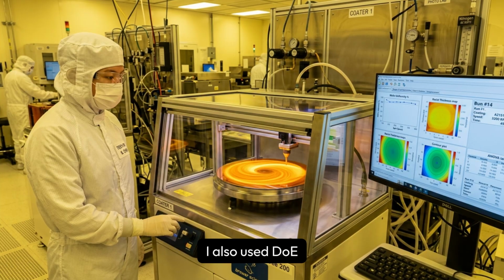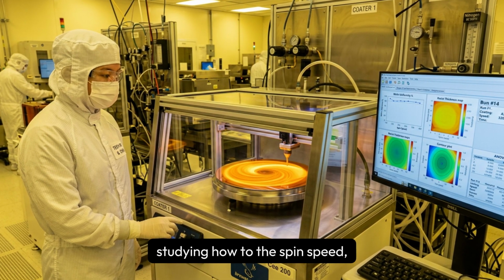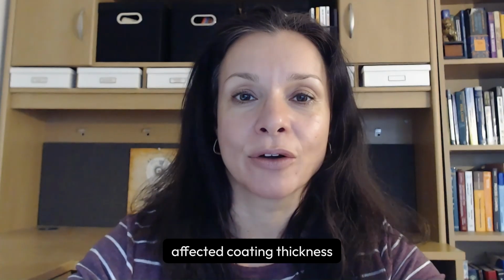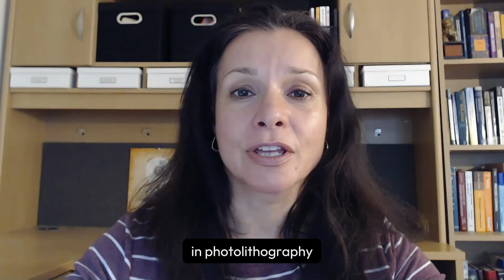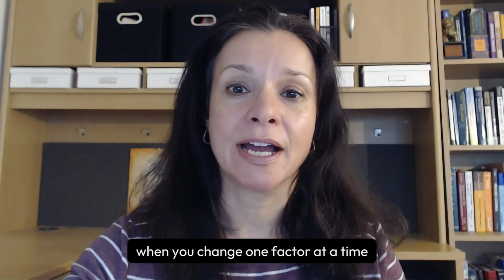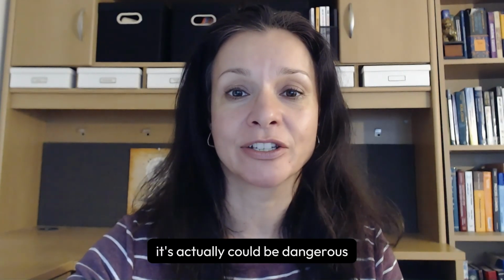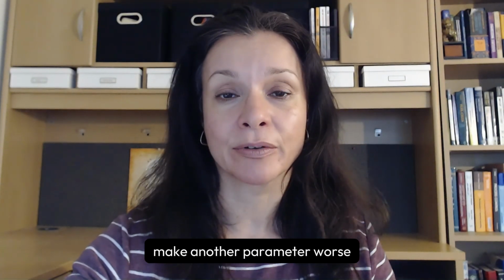I also used DOE for photolithography coating processes, studying how the spin speed, coating temperature, humidity, and material viscosity affected coating thickness and uniformity across a wafer. In photolithography, every micron, or in some cases nanometers, of thickness variation matters. So when you change one factor at a time, it's not just inefficient in this environment. It could actually be dangerous because you could optimize one parameter and unknowingly make another parameter worse.